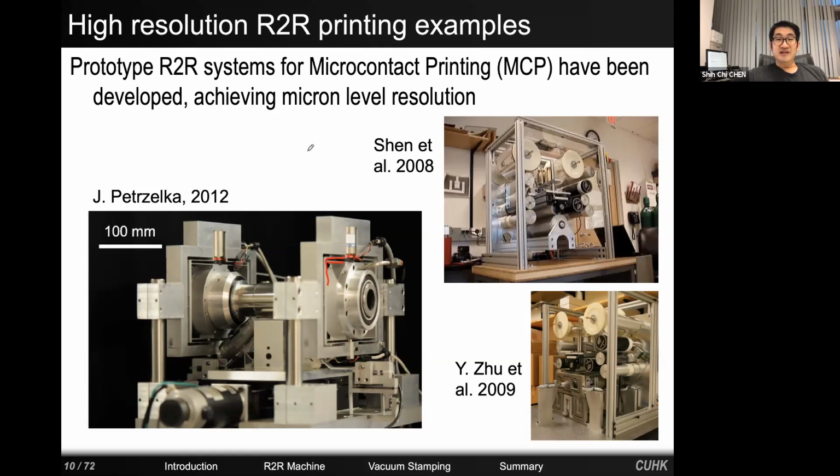The reason is at microscale, you cannot design and fabricate multiple parts and assemble them. You cannot assemble microscale parts, and as a result, all micro devices are made in one part, or monolithically. And this happens to be the most precise mechanical system to generate motions based on the compliance of the material as shown here.